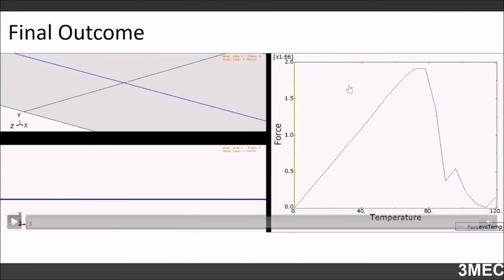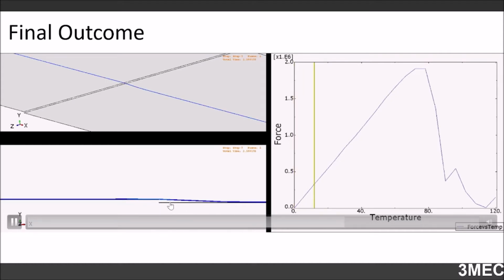Okay, and what we're going to achieve at the end of the day, so this is our pipeline. These are the two segments of the seabed, and you see the temperature is not rising initially. Step one is the case when you only apply the gravity load, so it's trying to establish a contact. You can see this analysis is going on. After 1 second, you see now it's in the stage where your seabed starts to move down. You see here as well. So this is the isometric view, this is the front view, and you can see the pipe also starts to go down with the seabed, and you can see there is some kind of imperfection.